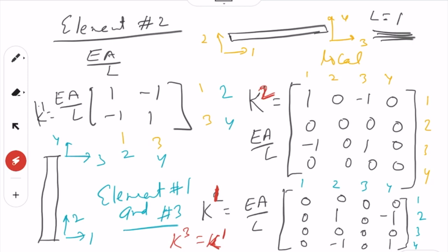So from here to here we have, from 1 degree of freedom per node system we have this one, 2 degrees of freedom per node we have, but we have local numbering. From here we have transferred that into global numbering. Global numbering, what we have? We have 7, 8, and then we have 5, 6. So this becomes 7, 8, 5, 6. Right?